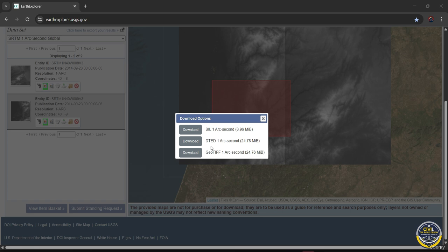It is a raster file that stores elevation values saved as a TIFF image with the georeferencing information. It works directly in Civil 3D and most GIS software, keeps projection and coordinate system data embedded, and is easy to share and visualize. It is the best choice if you are working in Civil 3D or ArcGIS.